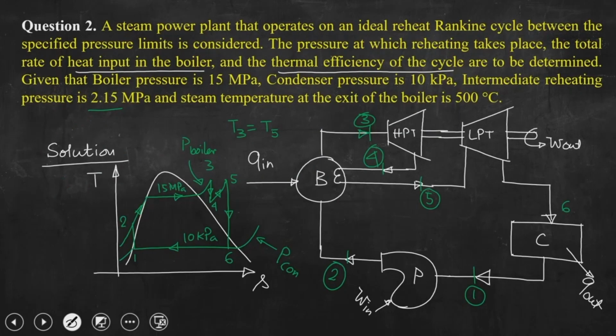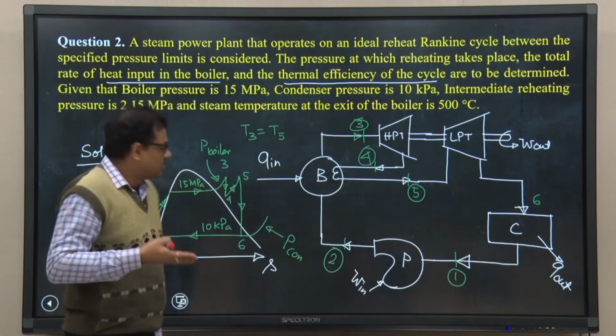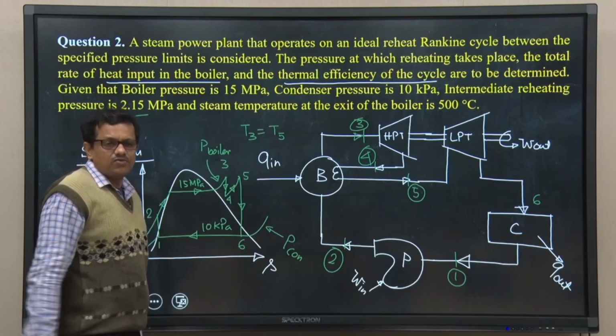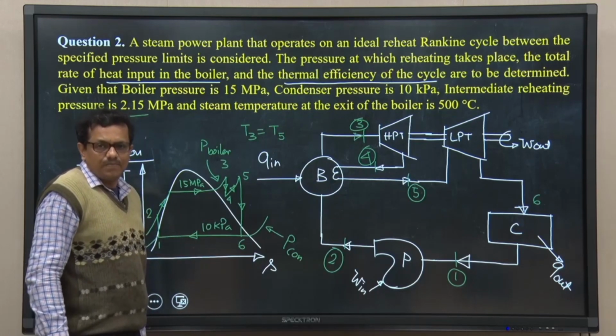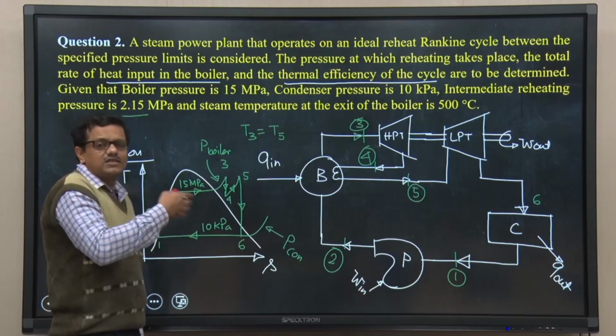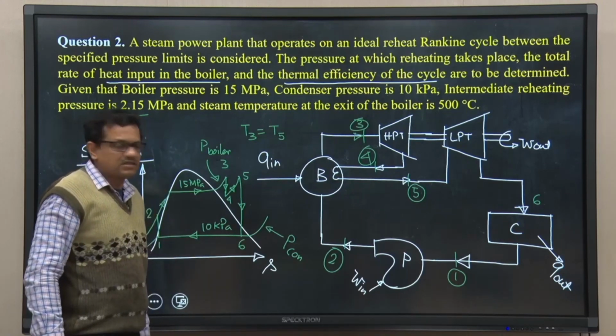The state at 1 is saturated liquid, that is again incompressible. So, we are pumping, we are pressurizing that liquid to increase its pressure, but this is incompressible, so rate of volumetric dilation is 0, we cannot compress it. Even then temperature is increasing because of the viscous effect, viscous dissipation.